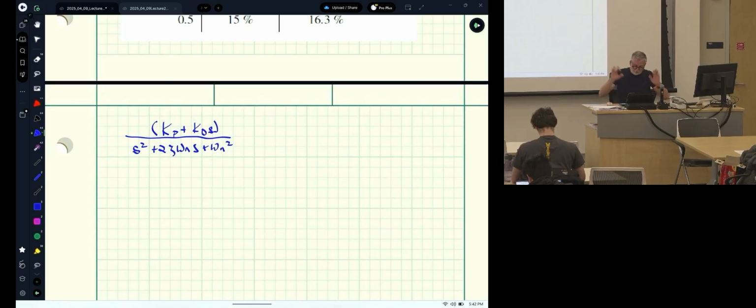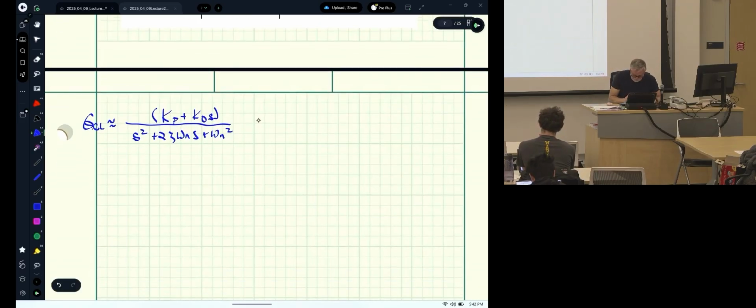There's another gain, but we'll worry about that in a second. But this is what our closed loop system is, approximately, okay? I'm leaving out a few terms, but the key thing is, oh yeah, there's the PD thing in the forward path. And the forward path numerator always comes through. So this, I'm going to write as KD times S plus KP over KD. Doesn't change anything.